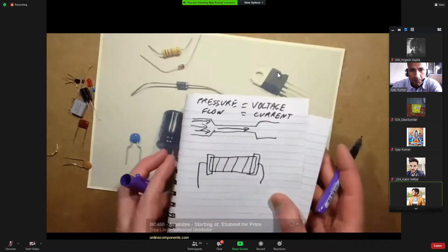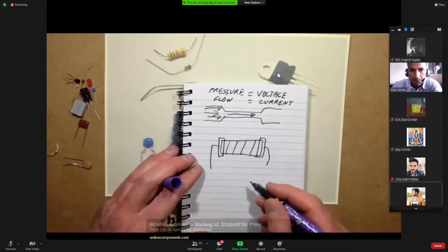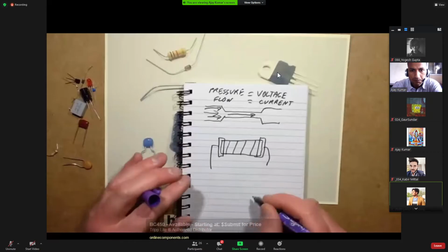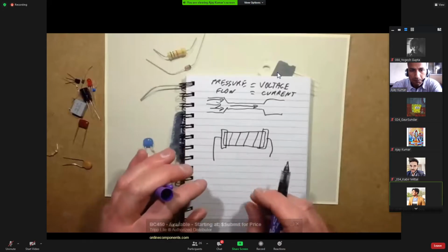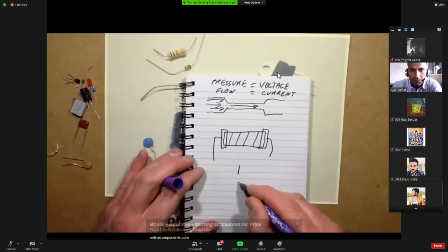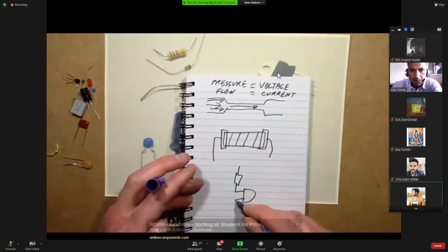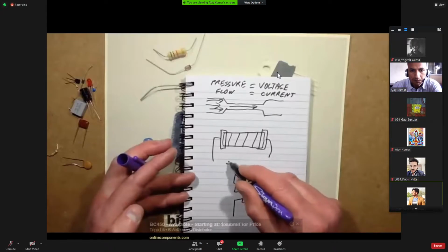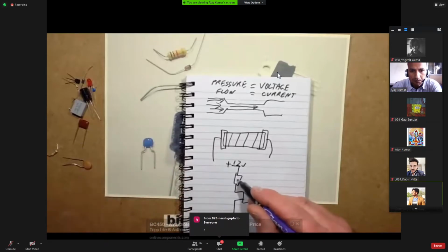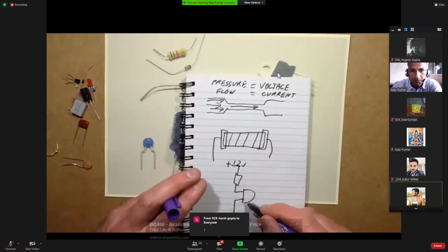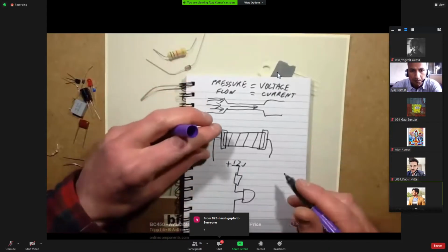Oh, I should continue and say about the resistors. The function of a resistor is to limit the current flow. Say, for instance, you wanted an LED to light from a battery. If you connected the LED straight across the battery, it would burn the LED out in most instances. But if you put a resistor in series with the LED, and you hook it across the plus 12 volts and 0 volts, then by choosing the resistor value, you can actually limit the current to the correct value for the LED. They're also used for things like time delays.